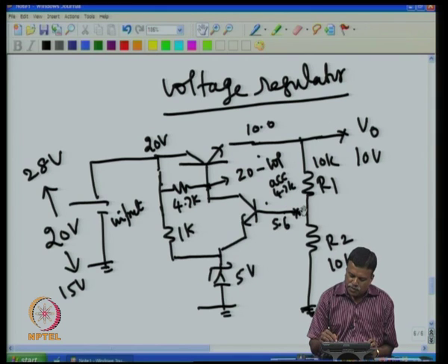If this sits at 5.6, I know that voltage across this, 5.6, means the base current is negligible. So, this current and this current are the same. So, across this it is 5.6, because whatever voltage is there across this, across this also it is 5.6. So, you will get voltage of 5.6 plus 5.6, that is 11.2 volt, and 11.2 volt is what it stabilizes here.